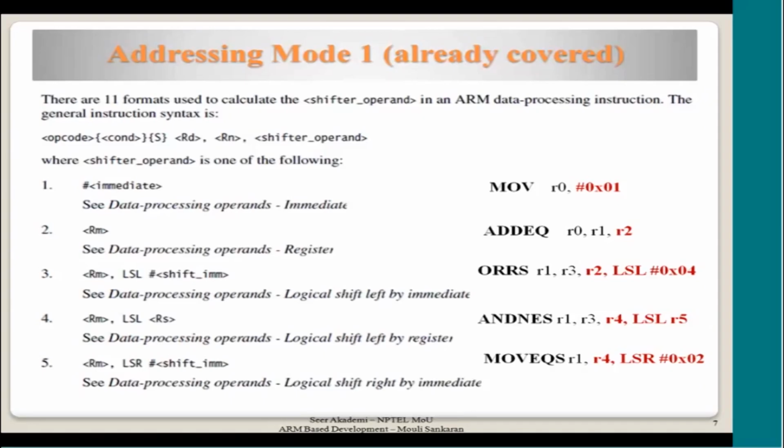Only the Rd, the destination register, is modified, and you are free to use any combination of registers. In fact, you could use the same register in all the places too. Though if you are using R15, which happens to be the program counter, there are some restrictions. Other than that, you will be able to use all the registers. So if you recall the data part of the ARM, all the register contents are copied from the value.